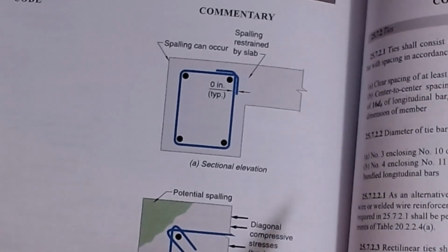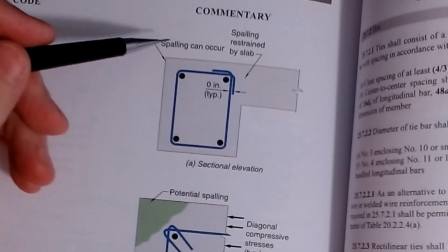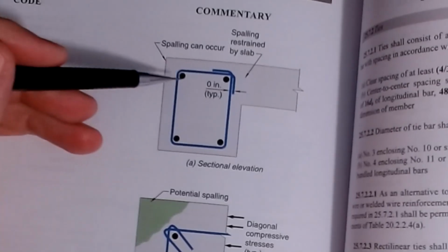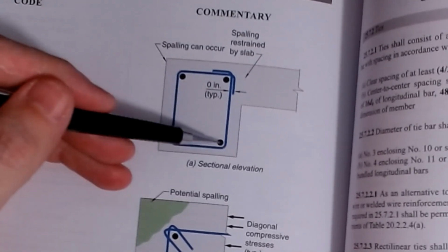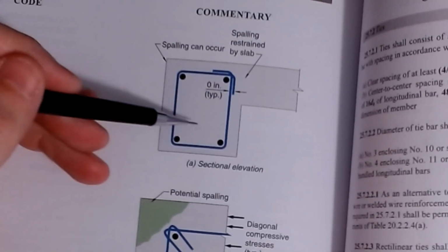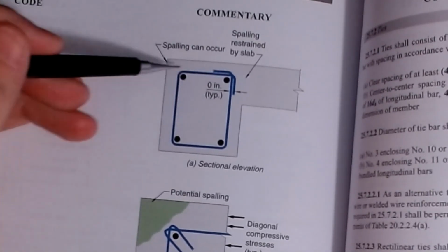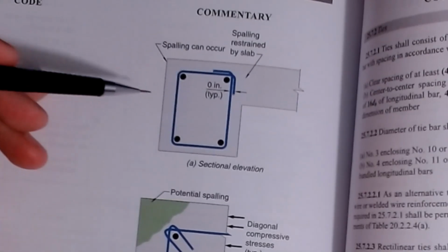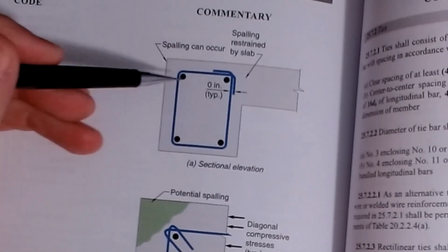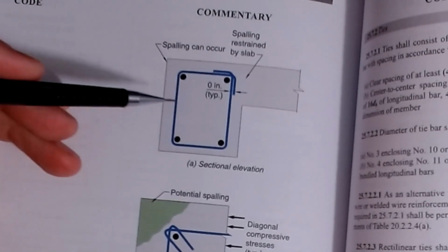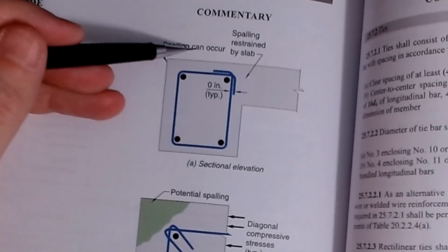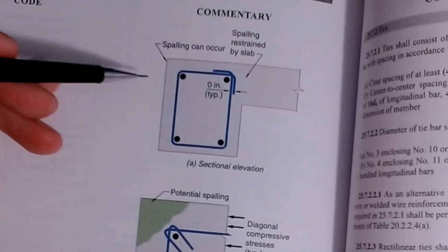Okay, and so that's what we're looking at. There are some requirements: it has to be a closed stirrup. It can be a stirrup made up of two parts, but they have to be anchored with 135-degree bends, and I'll show you those provisions and the requirements. But it has to be a closed stirrup, otherwise you cannot count on any steel for torsion, because it will crack the next section, and there won't be any torsional steel for it there.